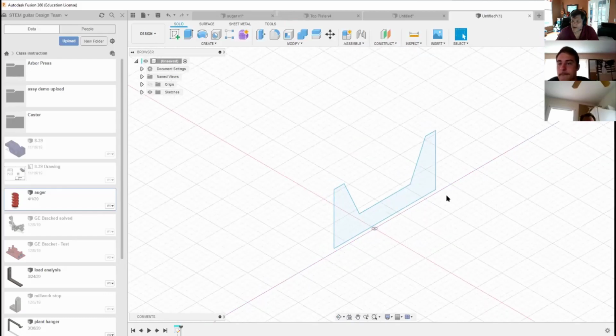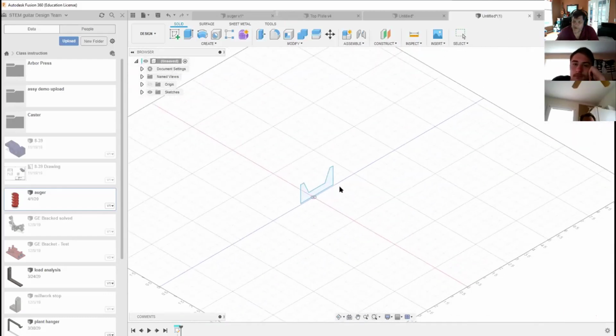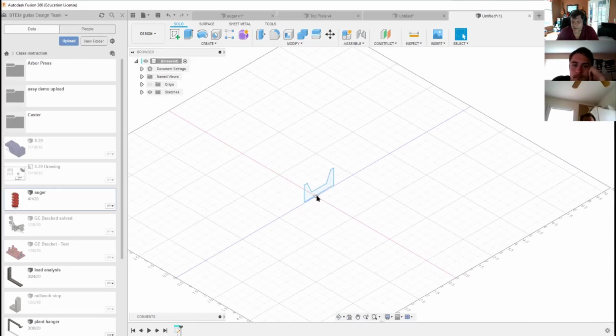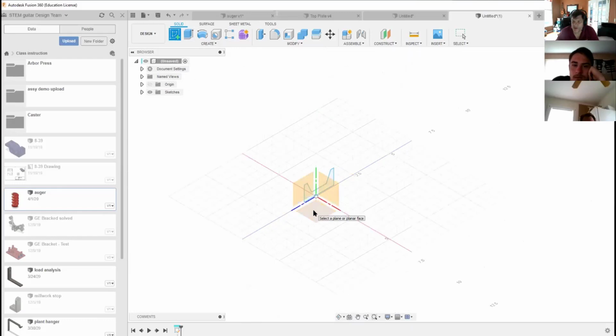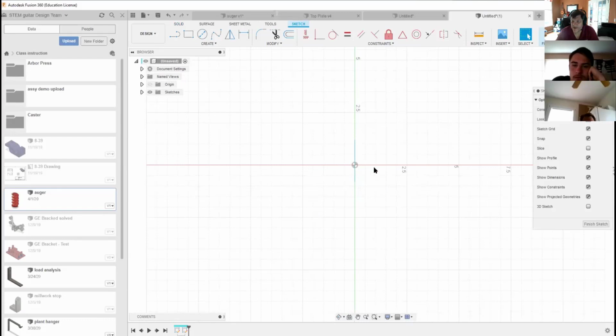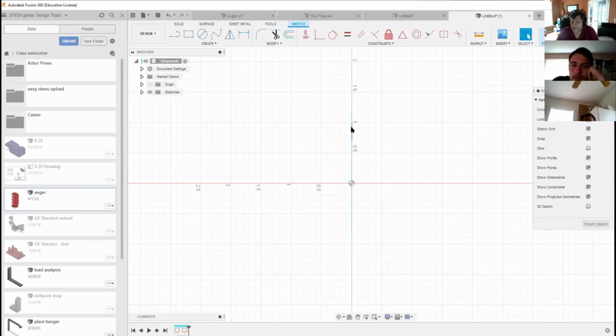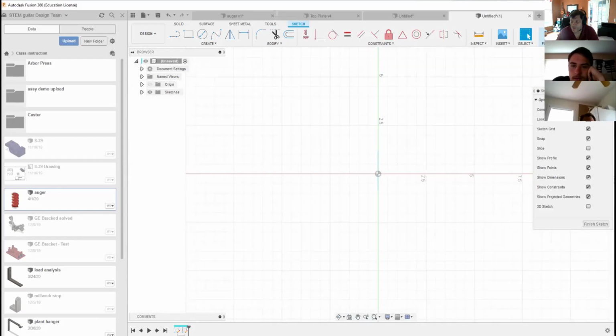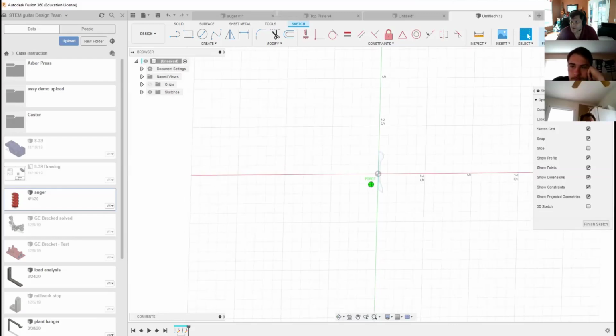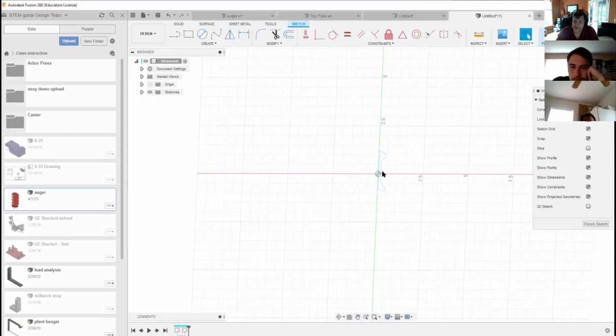And we'll finish that. Now we're going to do a sweep with this sketch. And what that means is that we're going to create a pathway for that sketch to follow. And so we're going to create a new sketch on a different plane, and that plane is perpendicular. So you can see that the current sketch is right here. It's a very faint line, but the sketch is here on that surface. And so if I tilt this just a little bit, you can see the original sketch.